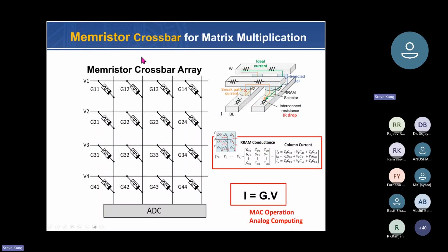Yeah, so I already mentioned many times, this is an ideal crossbar array, with input signals coming in from neurons, and then this is the output column. In analog signal, people use ADC, analog-to-digital conversion, but it's better not to use it. You have a neuron model here, outputting a signal here, and then receiving neurons. Depending on what neuron model you use, you may not need an A to D converter.